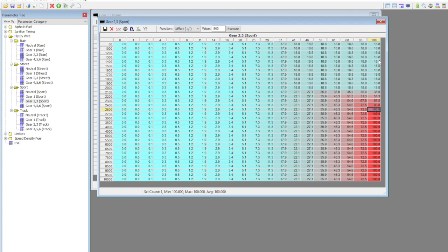You ask why? Well, engines are funny things. At low RPM, a lot of these high revving engines, which this essentially is, it's not like a car, which only revs to 6,000, 7,000 RPM. At low RPM on a motorcycle engine, it's found that keeping the throttle slightly closed actually helps power because it introduces a tumble and a swirl of the air into the cylinder.